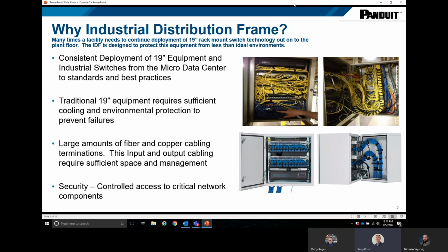Looking at the top pictures in this slide, the rack is in disarray. Proper cable management has largely been ignored, and ultimately this will affect the operational efficiency and the lifespan of the switches and other electronics like UPSs. This will affect the operational maintenance costs as well. These are actual pictures taken from a plant. It's also worthy to note that the cable routing came in through the top of the enclosure. So where is all the dirt, grime, and moisture going to settle and penetrate?